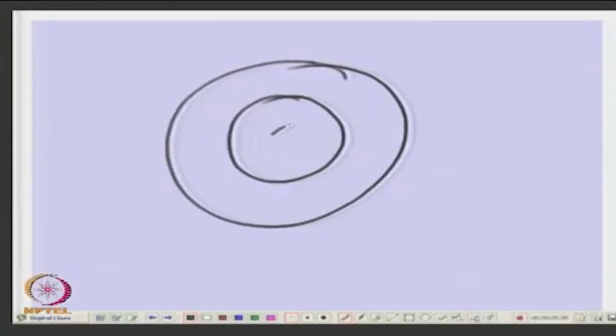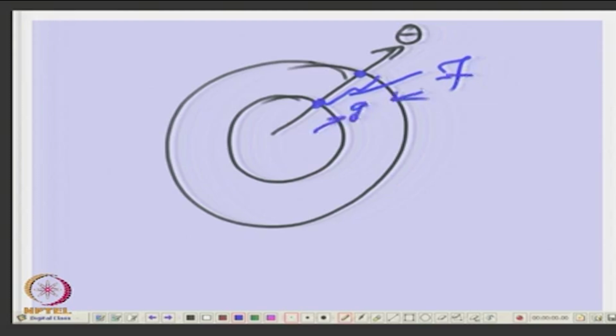So, you can always say, this is the MMF, let us say at some position theta. MMF is the magnetic potential difference, this is F. Stator surface has some x, rotor surface has y, x minus y is the MMF at that radial distance, and MMF drop F will depend upon the gap also. If the gap is more, MMF for the same H will be different, okay.